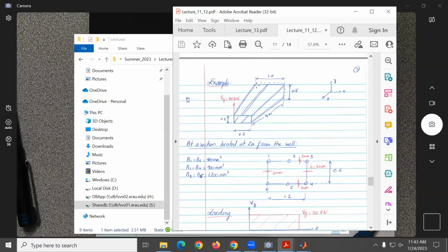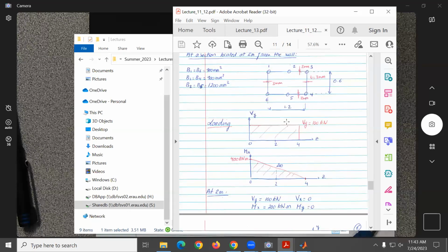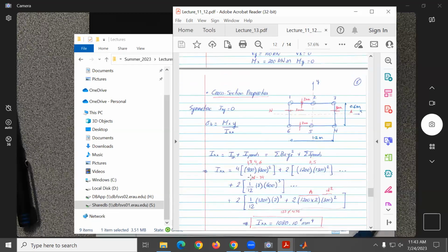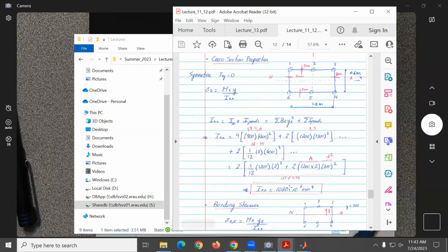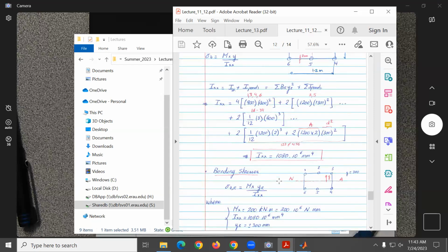Yes? Okay. So we have here, you see, it's taper on the Y, it's taper on the width, and in the spanwise direction. Okay. So we were asked, knowing this wing structure, wing box, having the shear force over here, find what will be the effect at one section that will be right in the middle at 2 meters. Okay. And that's what we solve. And when we solve, you see we have the load, the dy, and we consider here the IXX to be the I of the skin plus the one of the panels. Okay, so this is the stuff that's actually wrong, so that's why I redid it.